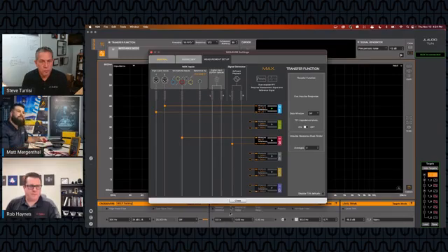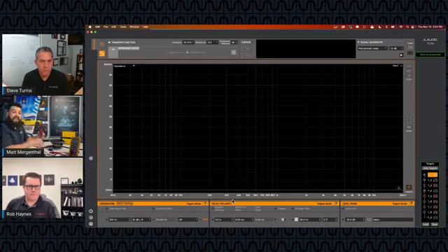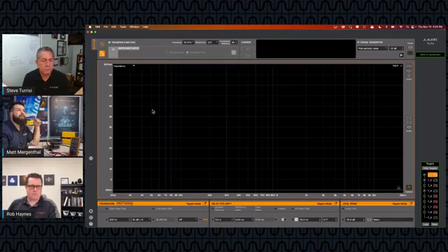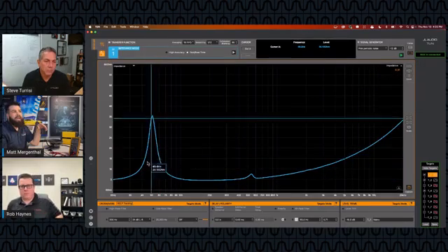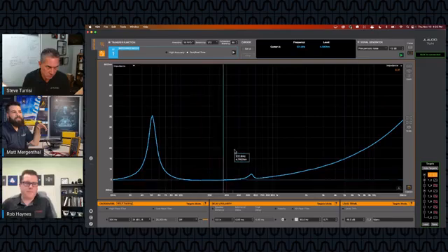So what I'm going to do here, I'm going to close out of that window. I'm going to connect my probes, my alligator clips, to both sides of the speaker, so connected to the positive and the negative. And then I'm going to go ahead on my graph here. I'm going to press the play button on my signal generator. And you'll notice I'm actually playing pink periodic noise, which is totally perfect for our measurement. If I go to the input combo box, I can play our data. And here you can see our impedance trace of this speaker.